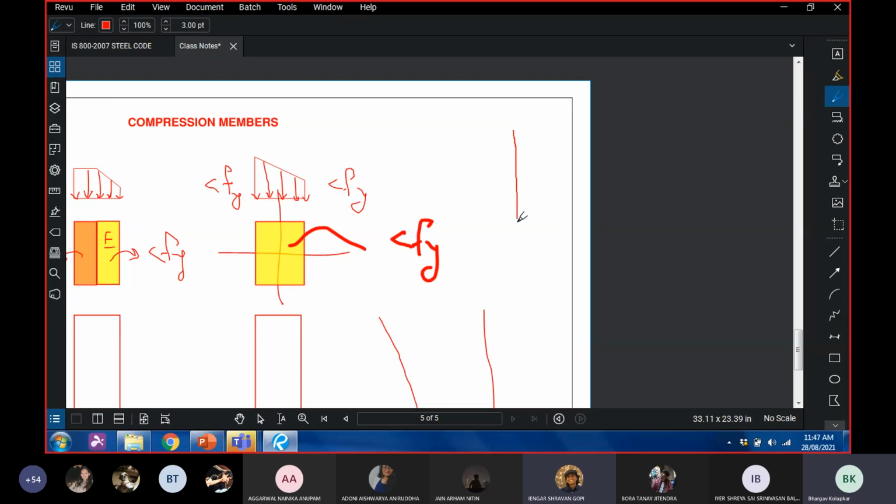Like a massive stone column, and the load is offset in a way that pulls it out of its socket and makes it fall over. The member is entirely fine, there is no deflection in the member. It has just turned and fallen over due to the seesaw of the load. It hasn't faced any distortion. Like the moment was too great.